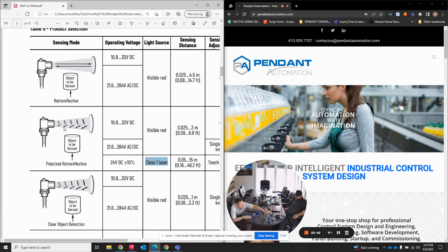And so I don't know if you can see here, you have the reflector. It's really the same bracket duplicated both sides, one side on each of the conveyor, and the sensor gets mounted on one side, the reflector gets mounted on another side, and you pretty much have X, Y, and Z control of this photo eye.